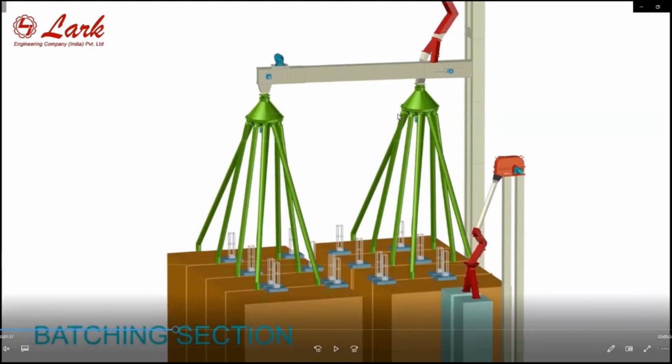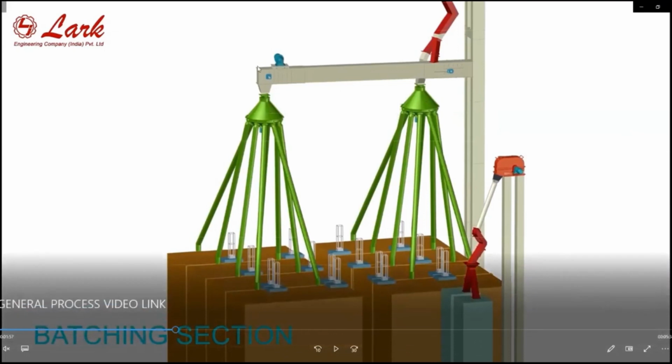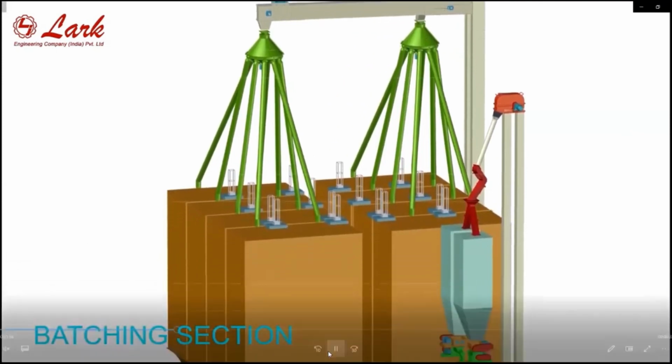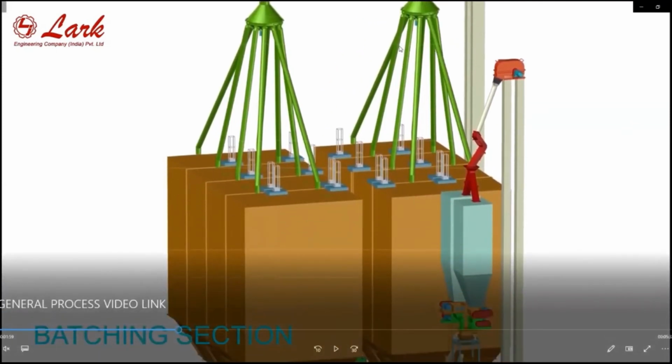Even with fibrous material like cattle feed and other fibrous materials, we have to check the angle of the chutes and the ducts. And this rotary distributor works with only a 1 HP motor. Only a 1 HP motor guides the material to all dosing bins.